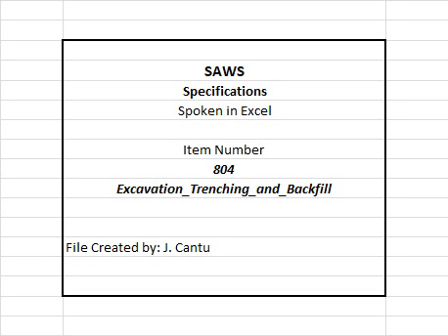Trenches in alleys actively being used by vehicles, such as trash pickup, vehicle parking, etc., shall be restored by grading and compacting to 98%, per TXDOT TEX 113 or TEX 114, or higher with a minimum of 4 inches of flex base materials for the entire width of the alley. Asphaltic materials shall have a compaction density of 95%. Alleys not actively used by vehicles shall be graded and compacted to 98%, per TXDOT TEX 113 or TEX 114, or higher from the top of the initial backfill to the bottom of the pavement section, then spread grass seed for entire width of the alley.